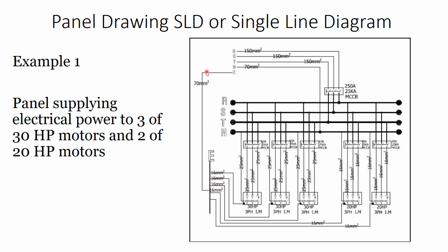Which takes all of the earthing at one point. The function of this one is that we earth the enclosure of the motor. So this one is the earthing for the panel. This one is the earthing for the enclosure, going here like this to the earthing bus bar. We take all of these as cables going to one single point for the earthing system.